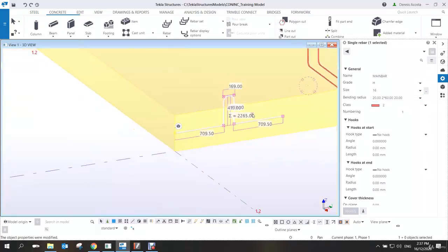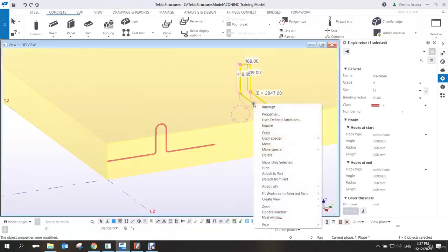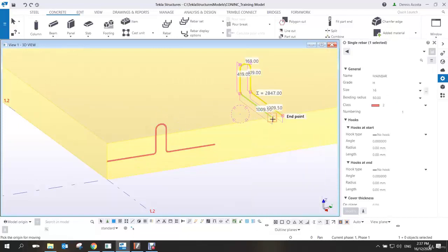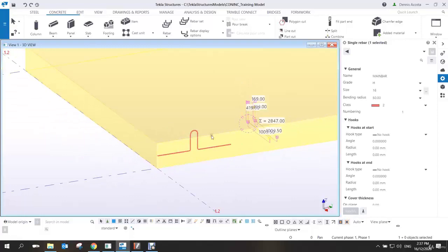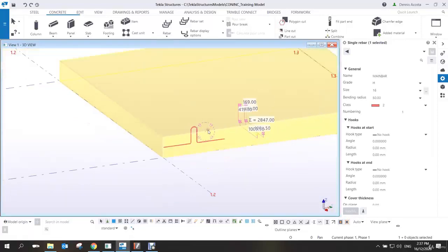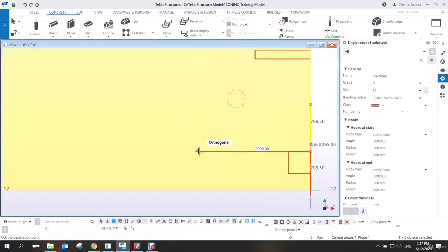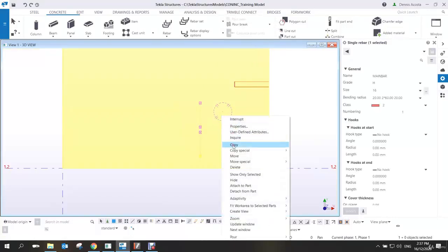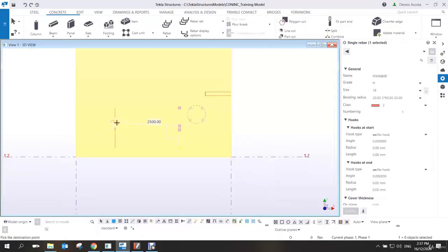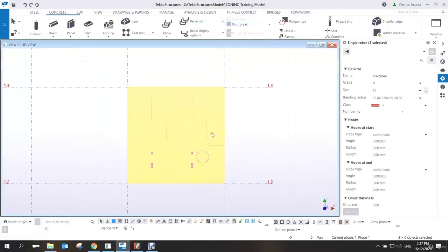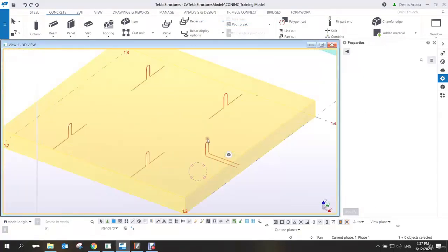Okay, and then I can now place this one to the position where I want to. So I'm going to move this one as well. Move it to 50. Then you can see the exposed one, right? So I can now place this. So this one, move say 2000 and then move 350 and then copy here and then here copy, then you have now the lifting anchor.